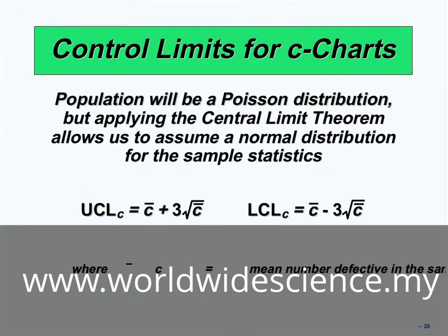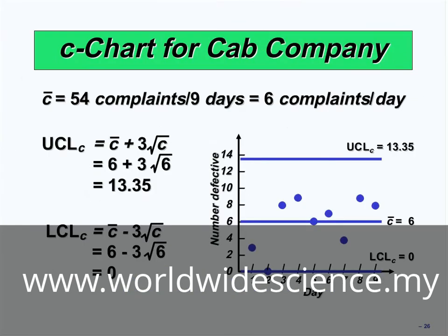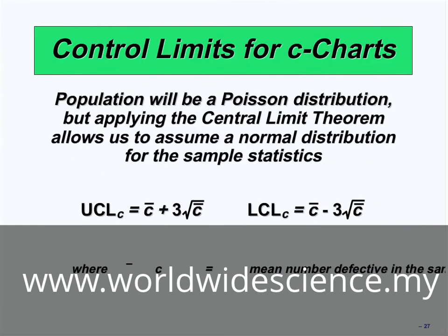In the C chart, we involve, like the P chart, the number of defectives. As I told you, in P chart and C chart, the number of defectives is important for us. But in R chart and X bar chart, we should have measured variables, for example weight, temperature, and something like this.